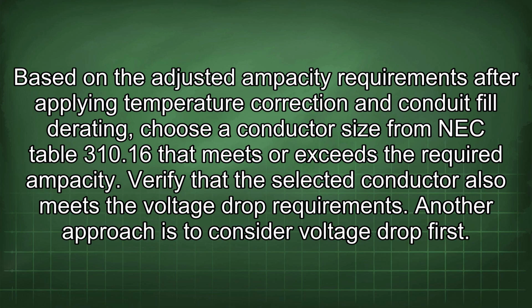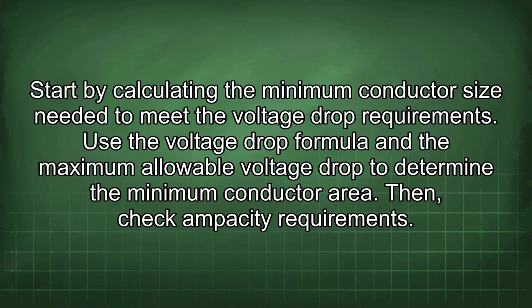Another approach is to consider voltage drop first. Start by calculating the minimum conductor size needed to meet the voltage drop requirements.